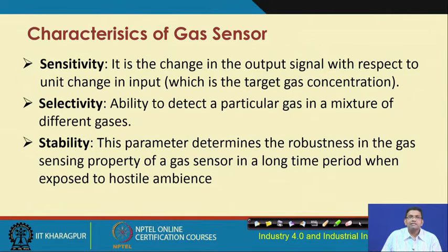So, there are different characteristics of the gas sensor. Sensitivity, that means it is the change in the output signal with respect to the unit change in the input. Input means the target gas concentration. If you are changing the target gas concentration, for a unit concentration change, how much is the change in the output signal with respect to it.